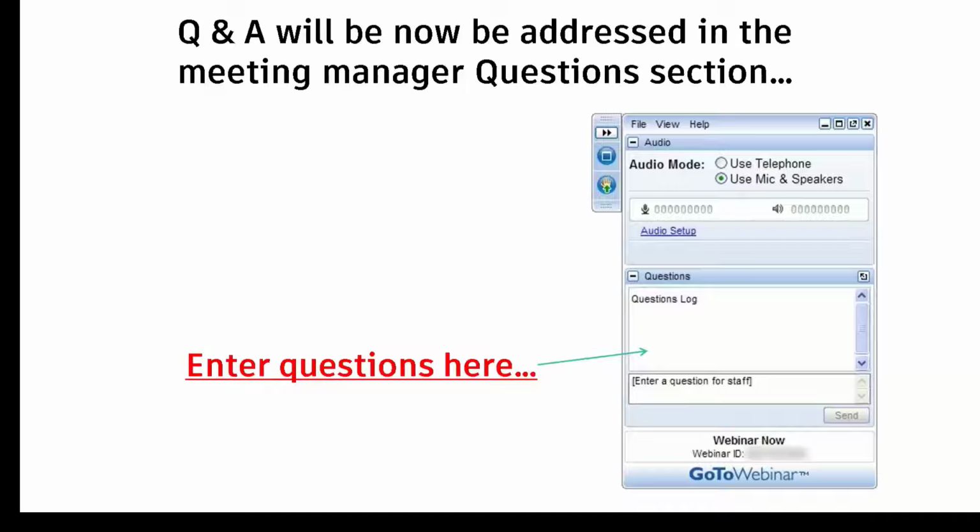So, Kendra, one question came up regarding the material assignments within Inventor. Do those have any effect on the NASTRAN materials? The material assignments you create, typically you're going to have those materials added to either the Autodesk library or the Inventor library, especially if you're going to be using that material across multiple IPT files. It's going to make life easier if you put it in a library. Whatever material you have assigned in Inventor, that material carries over, whether it's generic or it's a customized material. So the properties assigned to that material carry into NASTRAN.